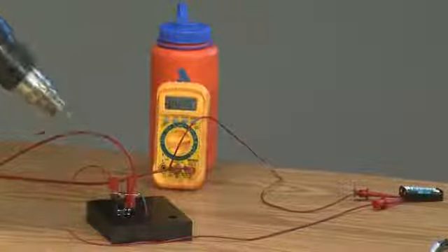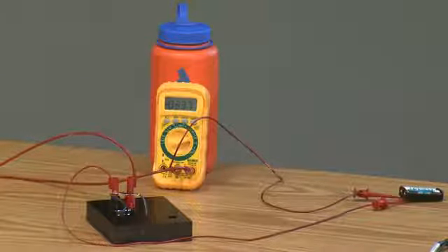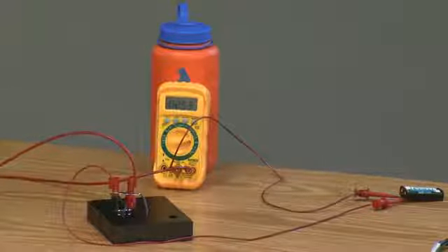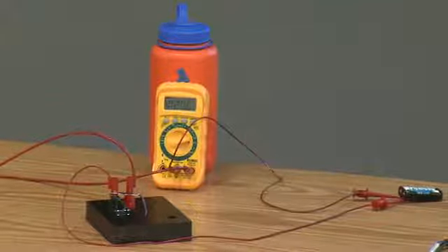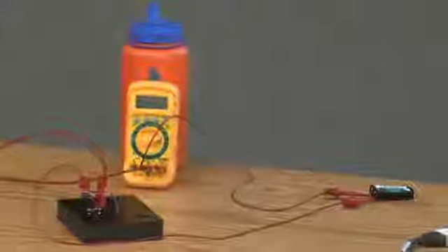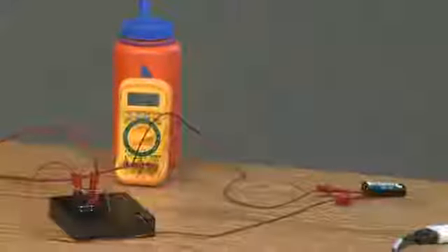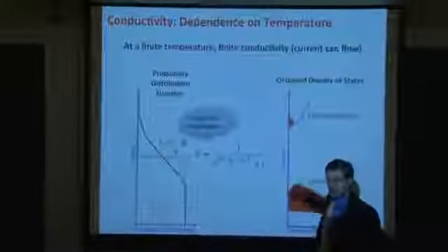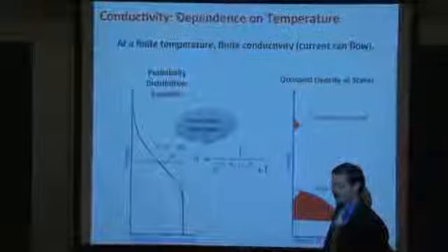It went up to around 50 microamps, and you can see it's dropping rather dramatically now. The current that the material is able to pass is increasing as a result of the increasing temperature, because you're exciting more carriers into the conduction band, leaving more holes in the valence band, and these are free charge carriers that are able to conduct charge through the material.